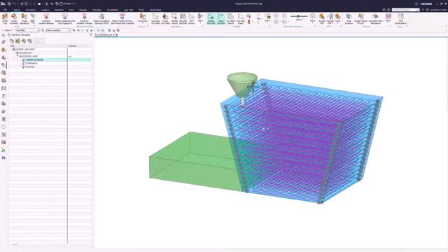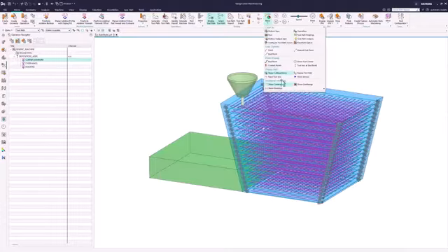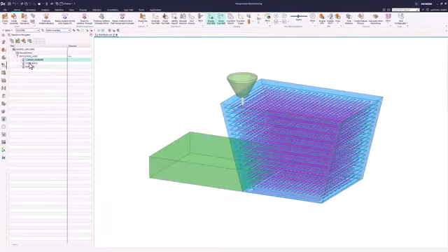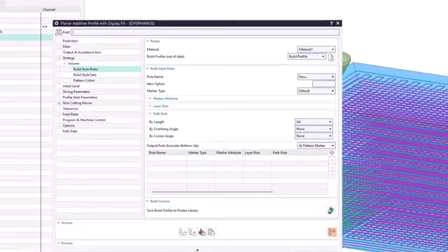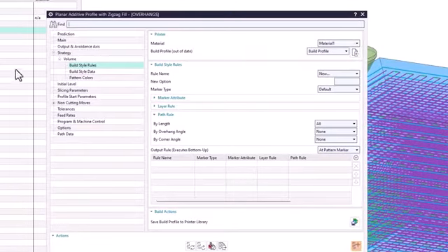Custom process parameters can also be applied to overhang areas. Overhangs for each point are calculated during operation calculation. Use the Build Styles tab to create a new rule for overhangs. The draft on this sample part is 15 degrees, so we will use 10 as the overhang angle.